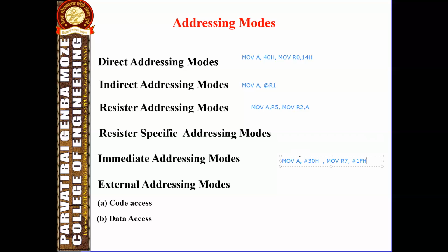These banks contain only 8 registers, and those are 8-bit registers. The addresses of a particular bank's registers in the memory run from 0 to 7. Hence we give the names R0 to R7 only, not any register named R8, R9, R10. No. The name of a register should be between R0 and R7 only.